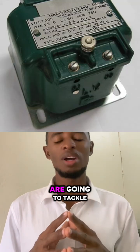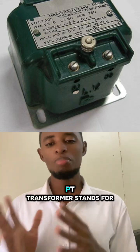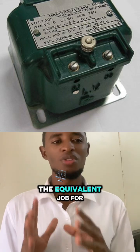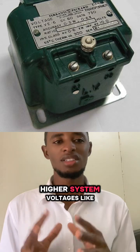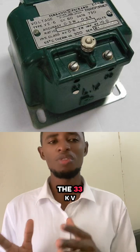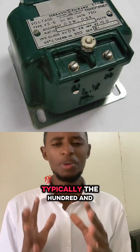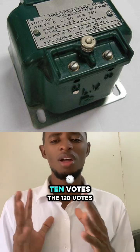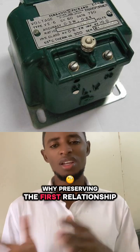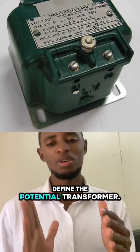And second, that is all about the current transformer. So we are going to tackle the PT transformer. PT stands for potential transformer. A potential transformer does the equivalent job for voltage, stepping higher system voltages like 11 kV, 33 kV, or higher down to a standard secondary value, typically 110 volts or 120 volts, while preserving the phase relationship. That's how I define the potential transformer.